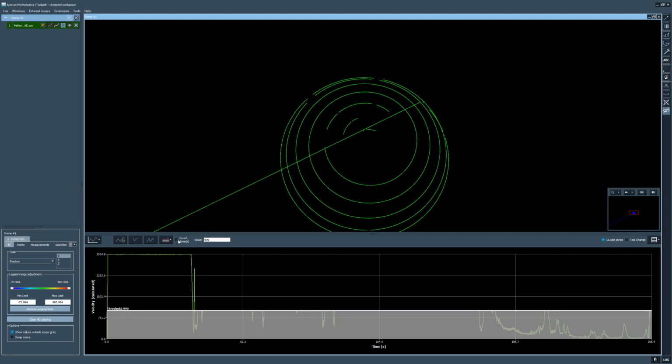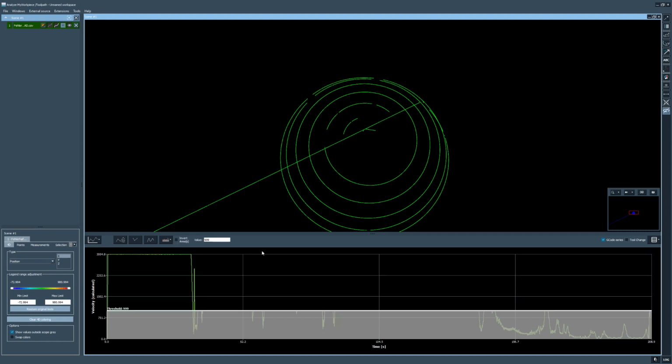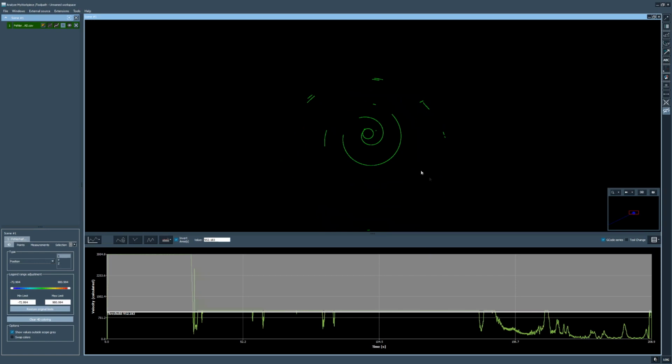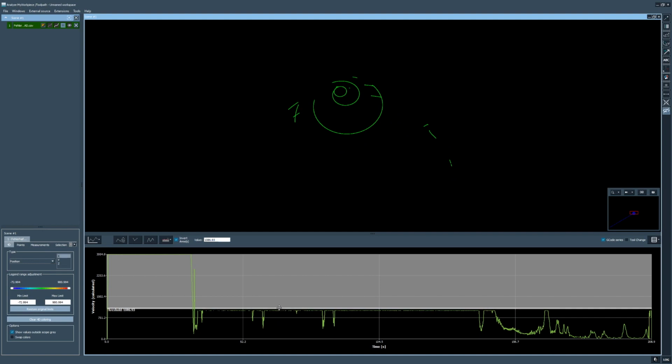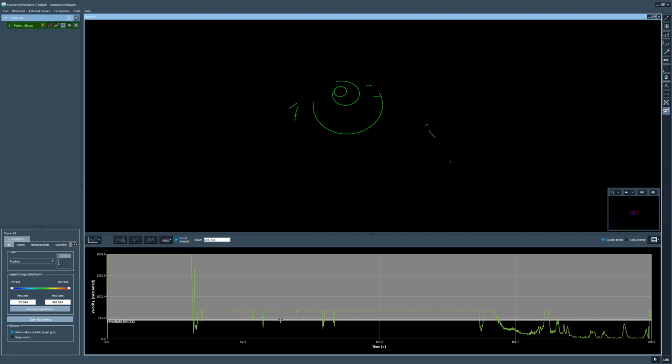And that now means that Toolpath is now inverting the threshold and showing to me the areas in my workpiece. Okay, I think 999 was a little bit too big. Let's go with 990. And Toolpath now shows me all the areas in the workpiece where the threshold was lower than 990 millimeter per minute. And this is very interactive, so if I move it back, I can see more of the workpiece again.